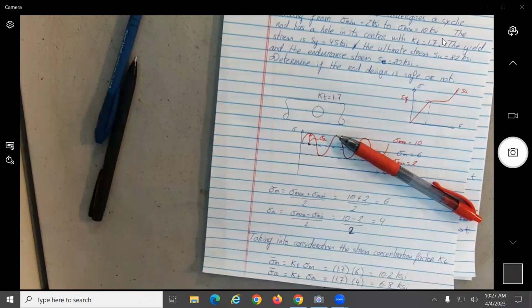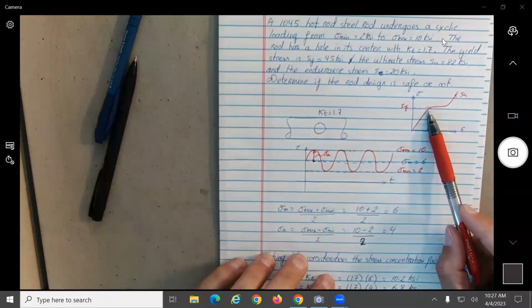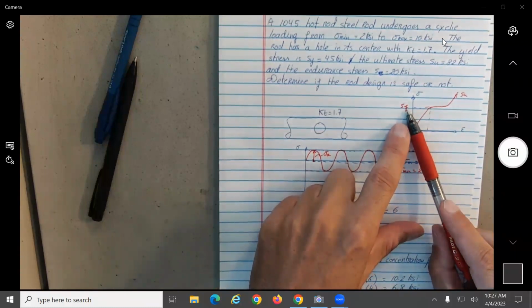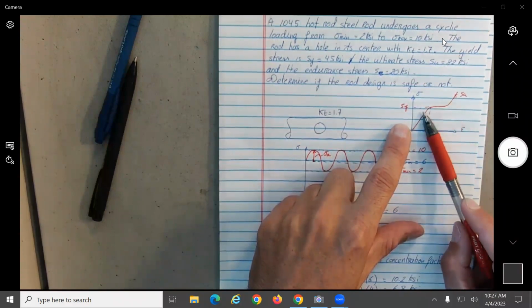Now maybe you have seen that or not, I'm not sure. But to make it even stronger, sometimes what do they do to the bars? Before putting the concrete, they elongate the bars. Why do they do that? The answer is here: if you elongate the steel bar, the resistance of the bar will not be the yield value. You can move it to the ultimate. Do you understand what I'm saying here?